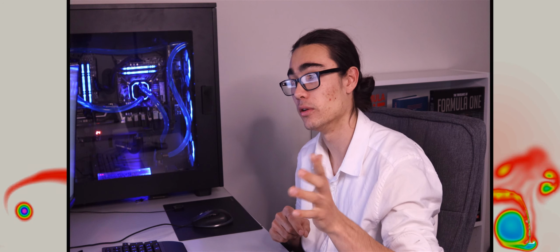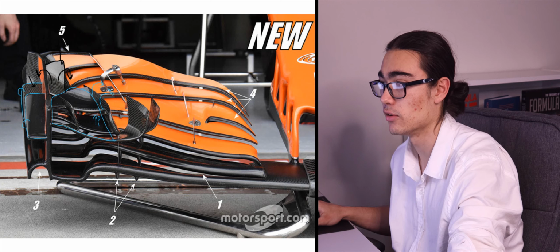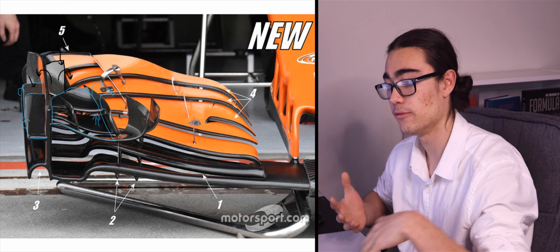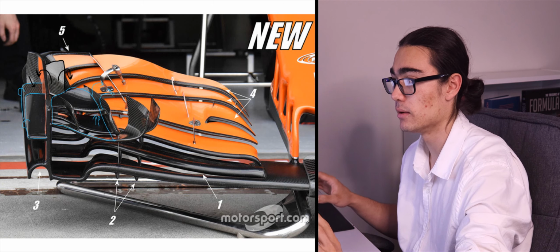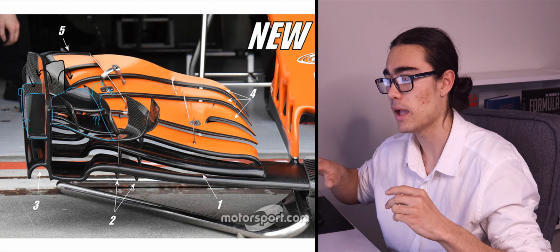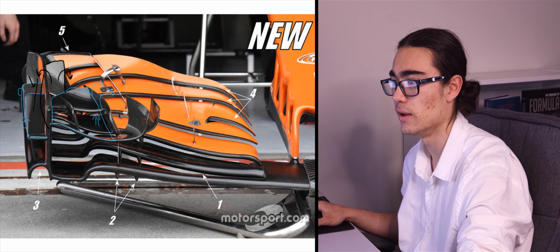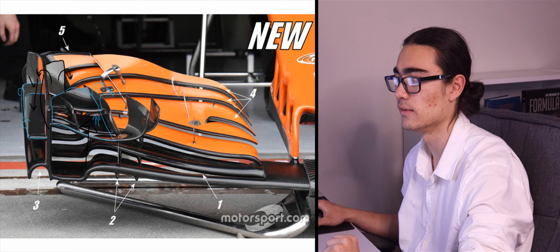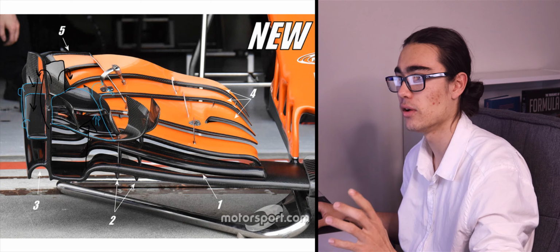Obviously this is going to be a lot smaller than the inboard structure right next to it. That's going to be a lot stronger because there's no end fence there to stop the vortex production. But generally, the reason why this interaction wouldn't be happening is because we've got this big end plate here, and the canards are so low down, and these vortices on the turning vanes are so high up. So perhaps that's why this interaction is not happening.